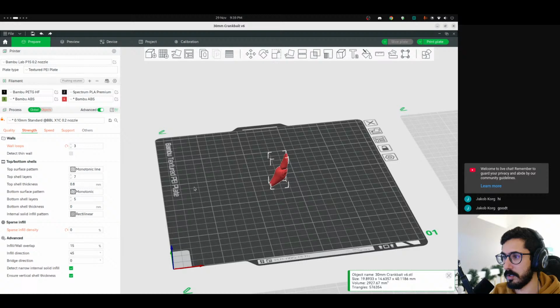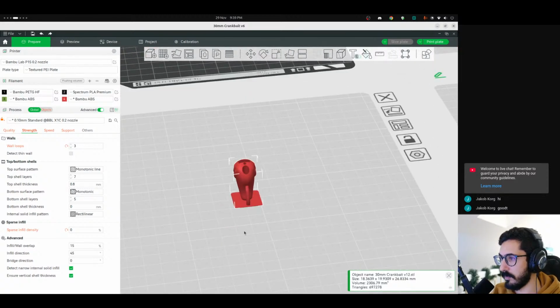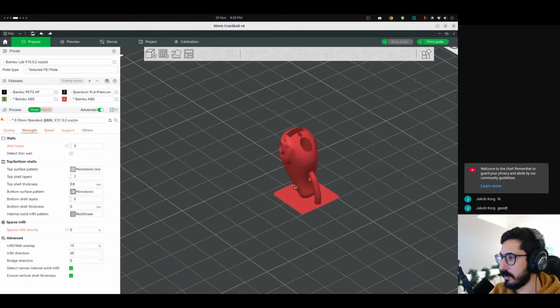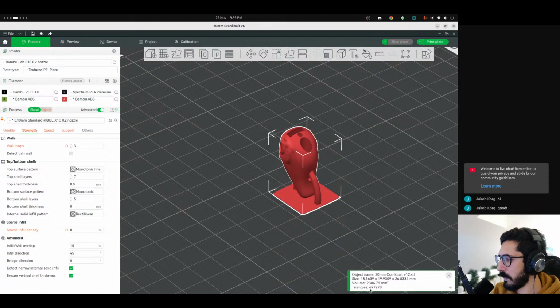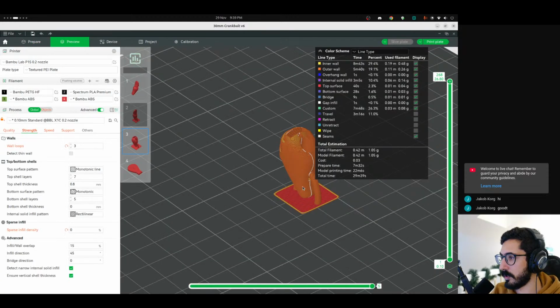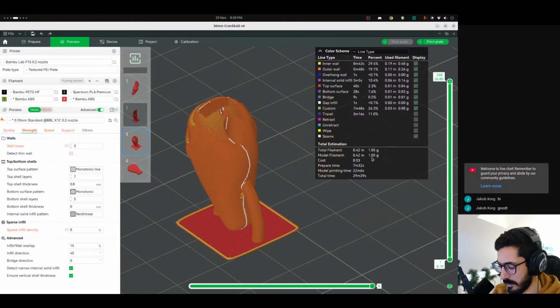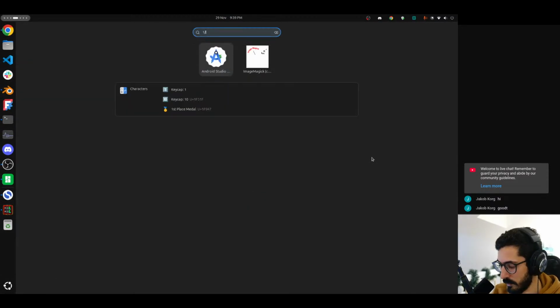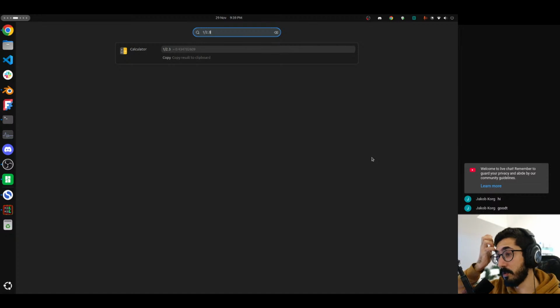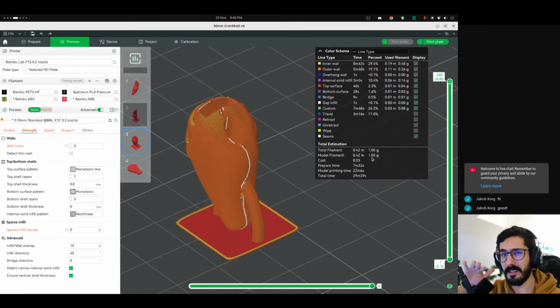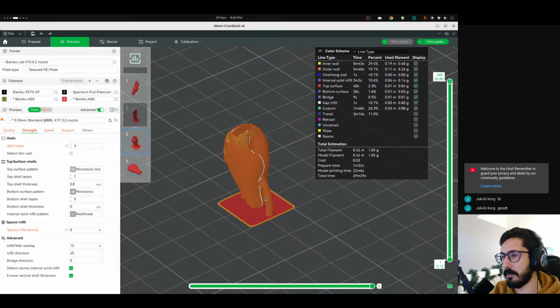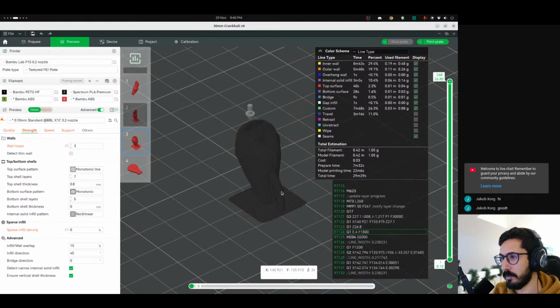And we can also check this other one right here. Let's see, this one right here says that it's 2.3 cubic centimeters, and if we check the preview, it's actually 1 gram. So that's 1 divided by 2.3. This is 0.4, the same. So that's in the regular wood territory. I think basswood is also 0.4.